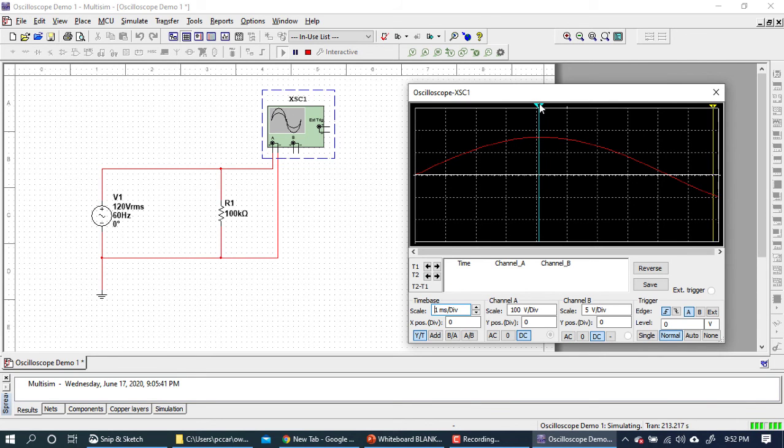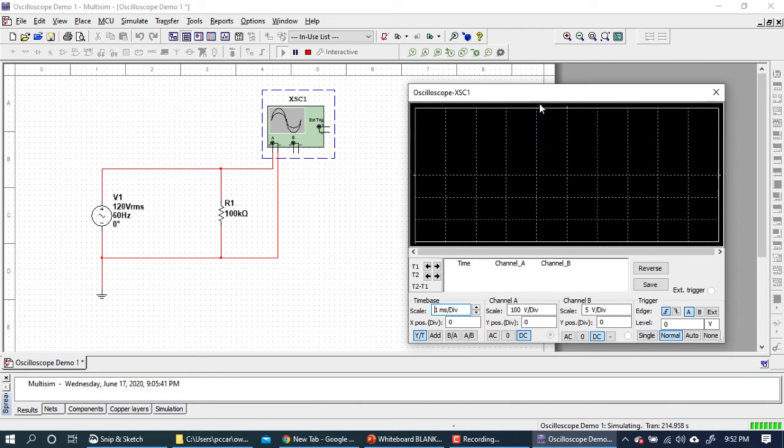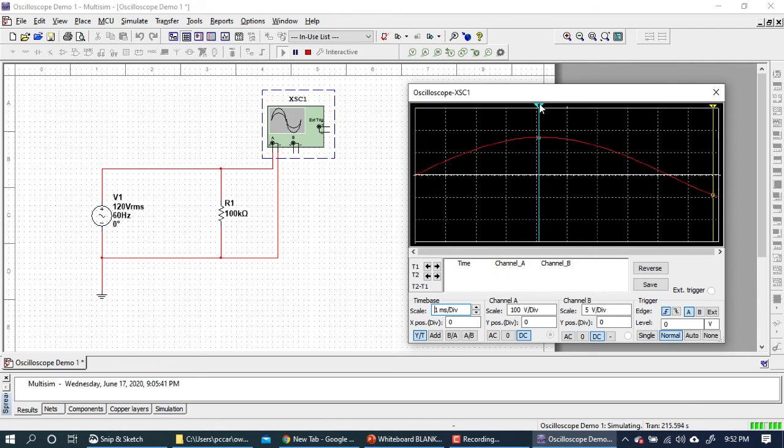The 45 degrees would be half of that. So the RMS value is the voltage that occurs halfway between 0 and 90 degrees, which is 45. So we would need to put our cursor at 45 degrees, which is halfway between 0 and 90. I don't know exactly. I'm just eyeballing it here, to be honest with you. But we could actually measure the time.